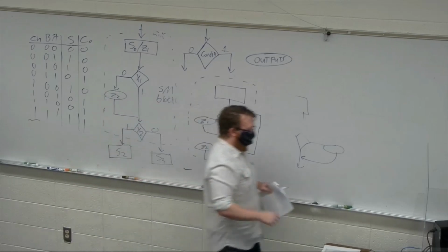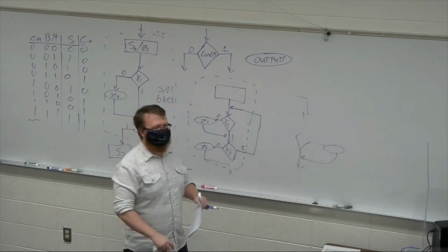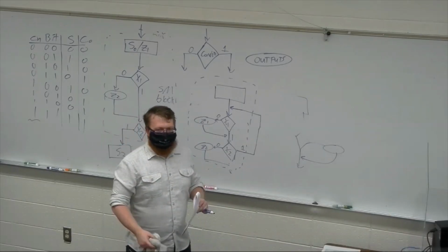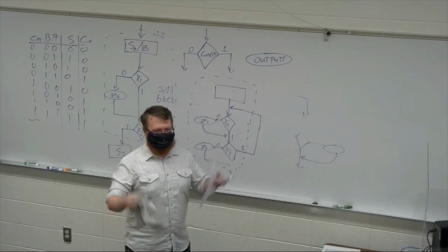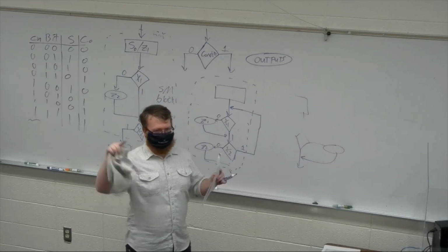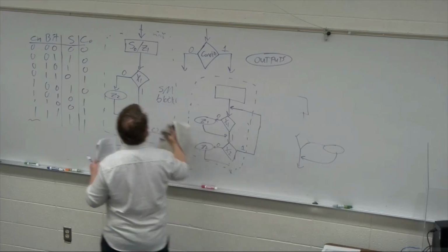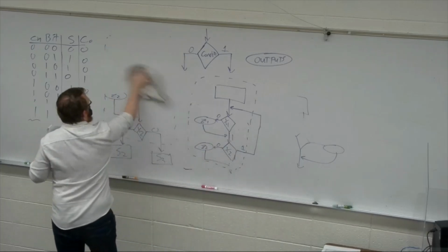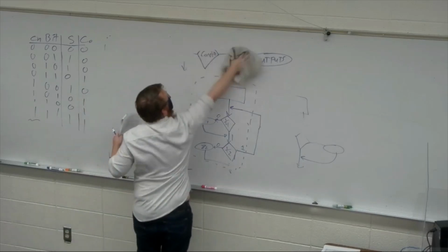Yeah. And this is where, in real life, we design a state machine to have some sort of reset state. You make sure your reset state sets everything how you want it to. A lot of times you'll turn the system on and just have an auto trigger reset to make sure you know exactly where the state is. Okay, so now that we understand those, I can use them to talk about other things because they're not that tricky.